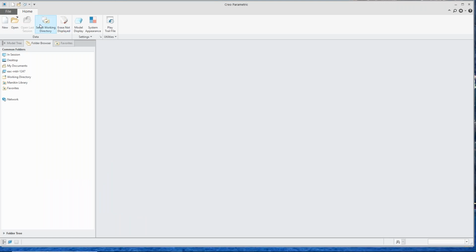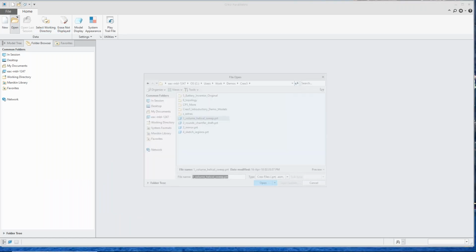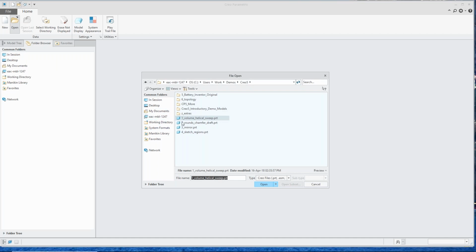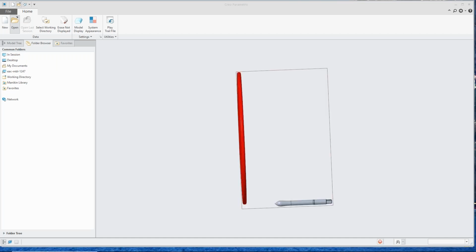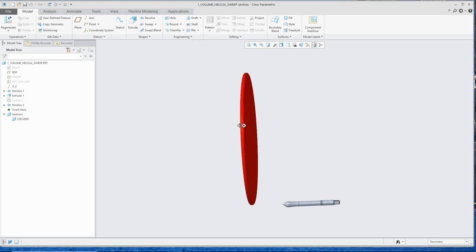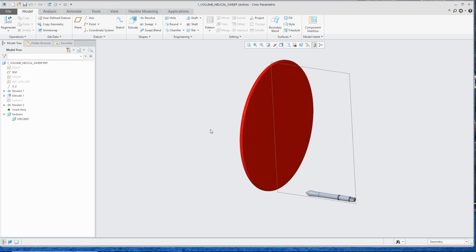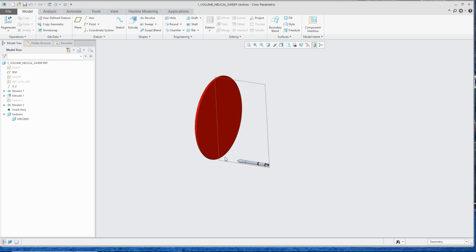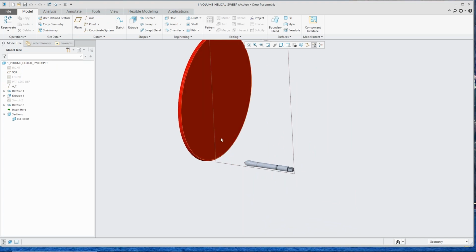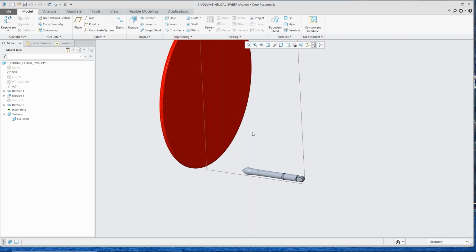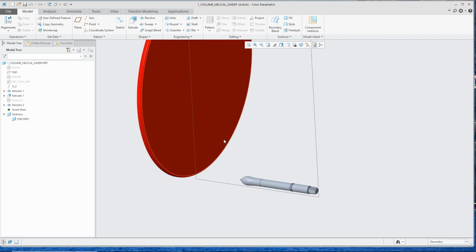Something else, again, talking about bleeding technology into Creo from somewhere else. One of the things we could do in flexible modeling, we could bring in a step file or a non-parametric file, and even if it had rounds on the geometry, we could still add draft onto the surfaces. What it was doing in the background is it would turn those rounds or chamfers off. It would highlight them in green, saying, hey, I recognize these as rounds or chamfers, allow you to manipulate the surfaces, and then it applies those rounds and chamfers back on to those new edges.